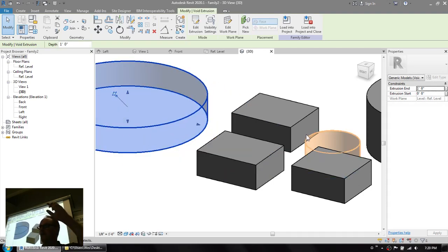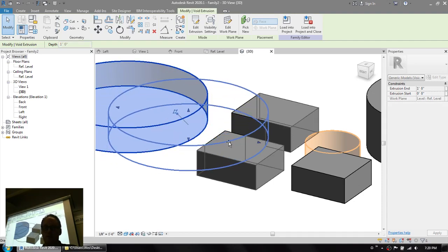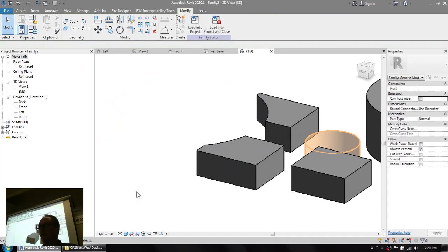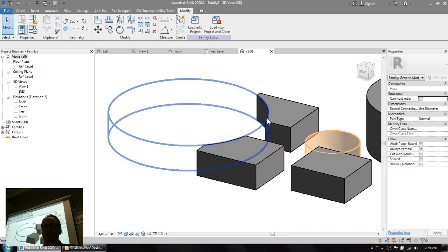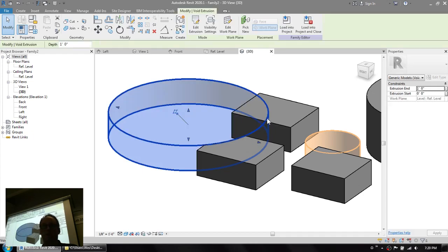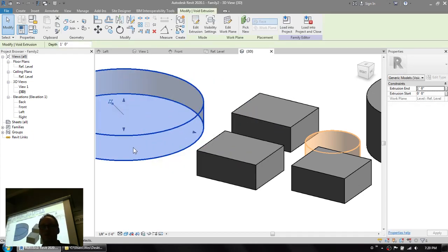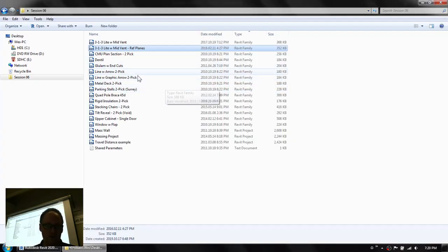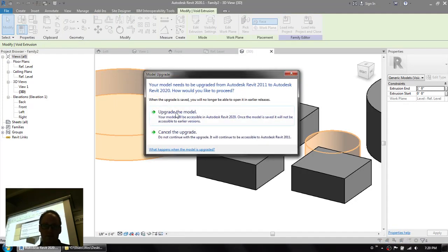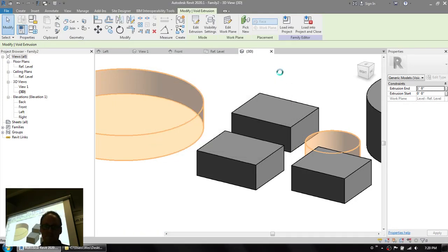And so we have length parameters, dimension parameters, that will grab that void and just move it out of the way when we don't want it to cut something, and then it simply won't, just because it's not there, right? So Mr. Miyagi told us that the best way to avoid solid is to not be there. So by moving our voids away from our solids, that's the way that we can control whether they're present or not.